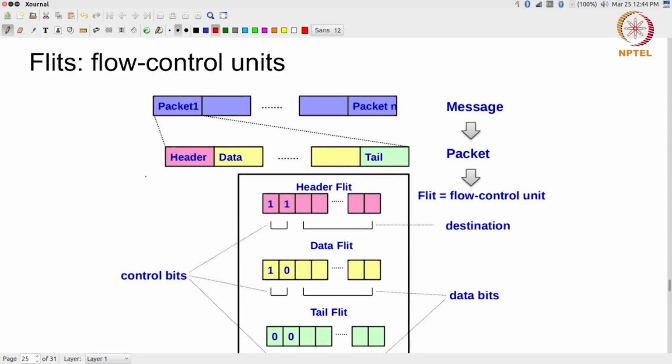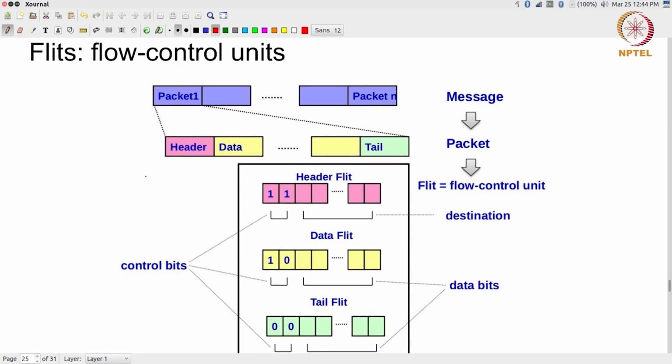Beyond that, we essentially bring in this concept of a flit, right. What we are saying is, I have a packet, but even a packet which might have been suitable for, let's say, an Ethernet packet, for example, can be up to 1500 bytes or so, right. Whereas the kind of packets that I might want to transfer when I am sending data around inside a chip, maybe I want to send smaller packets, right. So what you do is take packets and break them up into something smaller called flow control units, usually referred to as flits, okay. So a flit is essentially a fixed size small packet.